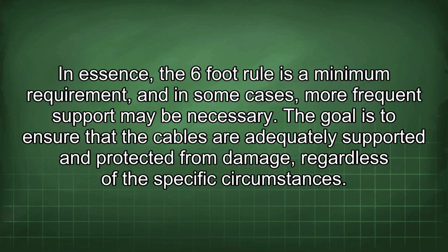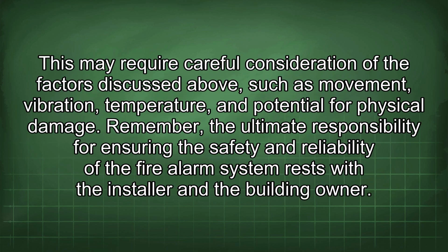In essence, the 6-foot rule is a minimum requirement, and in some cases, more frequent support may be necessary. The goal is to ensure that the cables are adequately supported and protected from damage, regardless of the specific circumstances. This may require careful consideration of the factors discussed above, such as movement, vibration, temperature, and potential for physical damage.